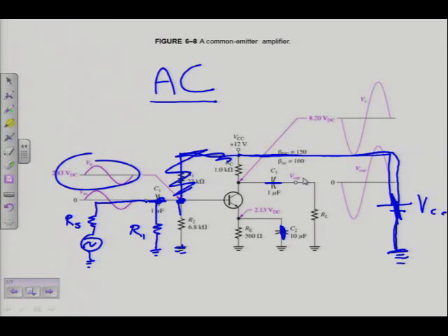So when you go to the lab and you are issued with all the components to build the circuit, I can't remember, I think the signal gen there is a 50 ohm internal resistance, then please don't go to the lab technician and ask him, sir, I didn't get the 50 ohm resistor. Because you won't find it, no? It's the internal resistance of the source. Alright, but anyway, so we sorted out that part of the circuit.